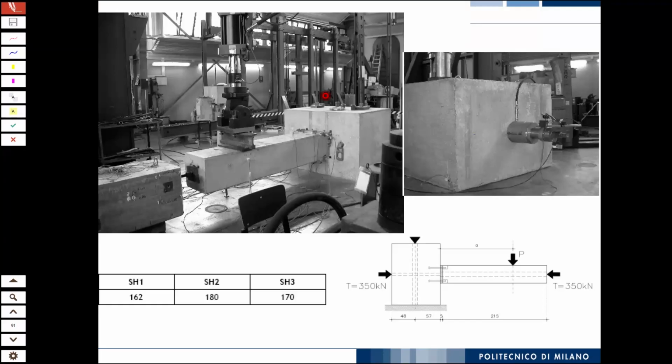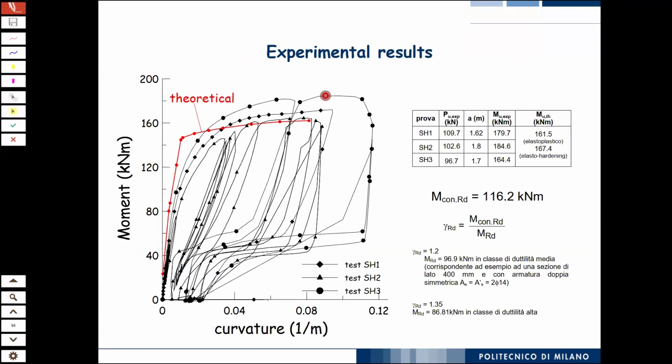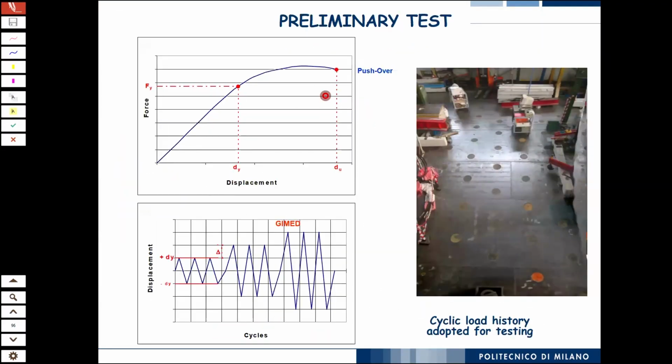You see here, these are anchoring bolts, and actually you see here, these are anchoring holes that we have in the floor of our lab. I can probably show, you see, this is a view from the top. Our floor, which is about 1 meter thick, has these anchoring holes. They are arranged according to an equilateral triangle network, and the distance is 1 meter from one to the other.